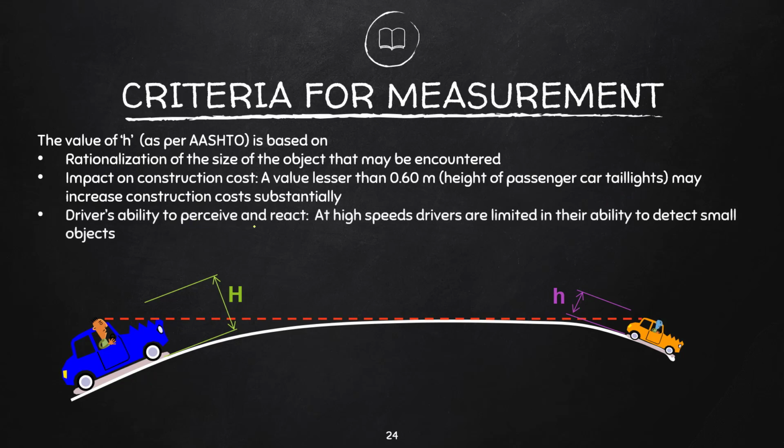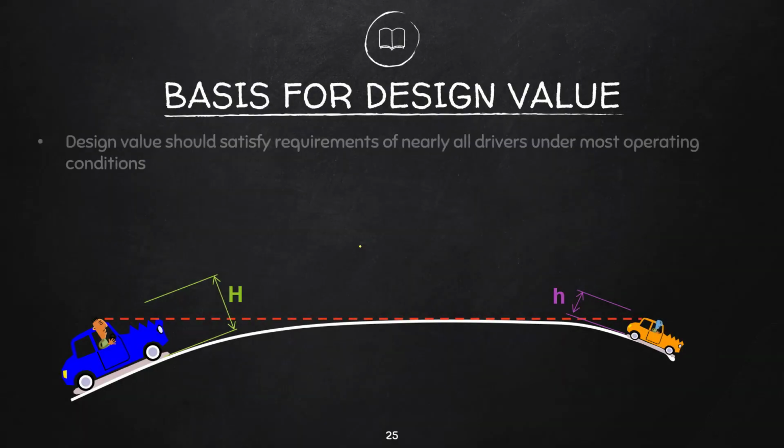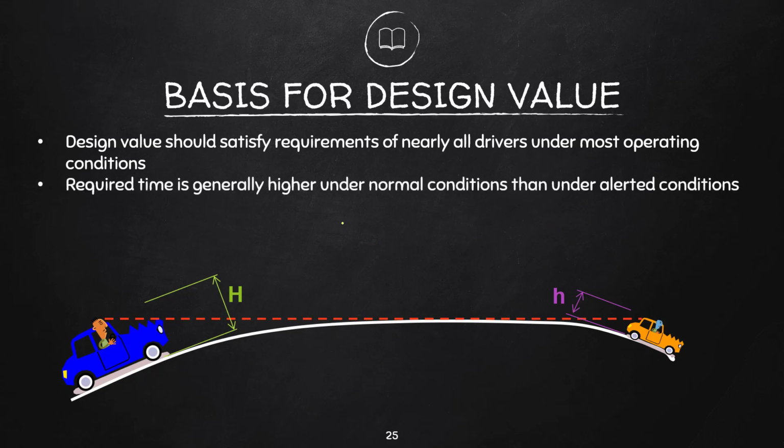Drivers' ability to perceive and react: at high speeds, drivers are limited in their ability to detect small objects. Of course, we have discussed that in the previous modules. Design value should satisfy requirements of nearly all drivers under most operating conditions. The required time is generally higher under normal conditions than under alerted conditions.